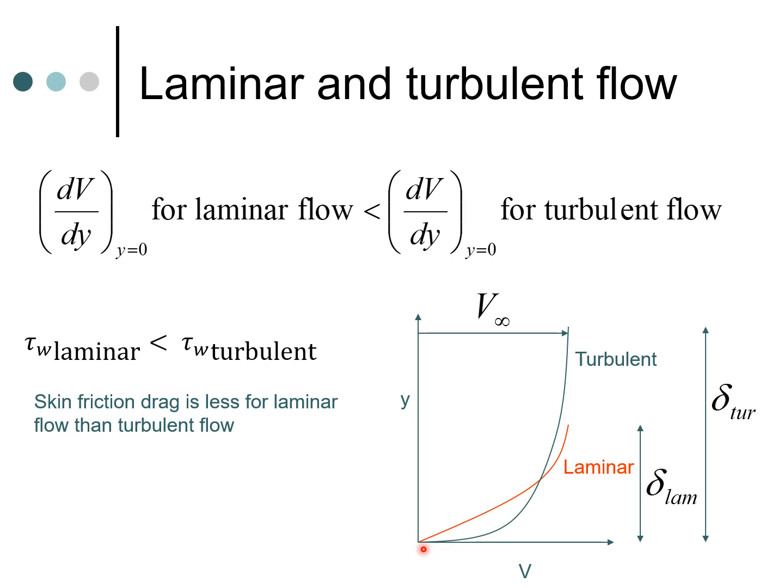If we see the velocity profile also, for the turbulent boundary layer the velocity goes somewhat like this, and in the laminar boundary layer it is given by the red line here. Remember that at the end of the boundary layer, the velocities are going to reach the same value, which is the free stream velocity, or in the case we were considering, the velocity v2 here.